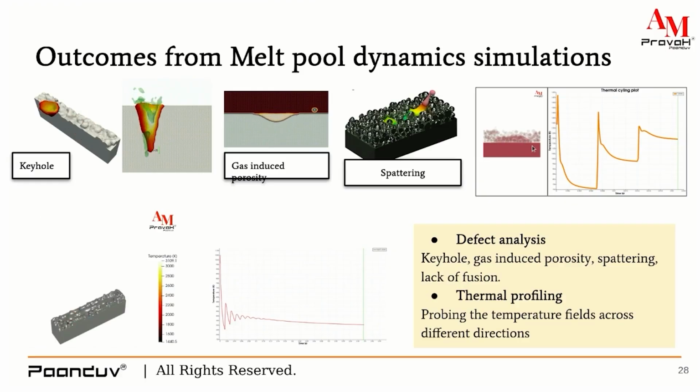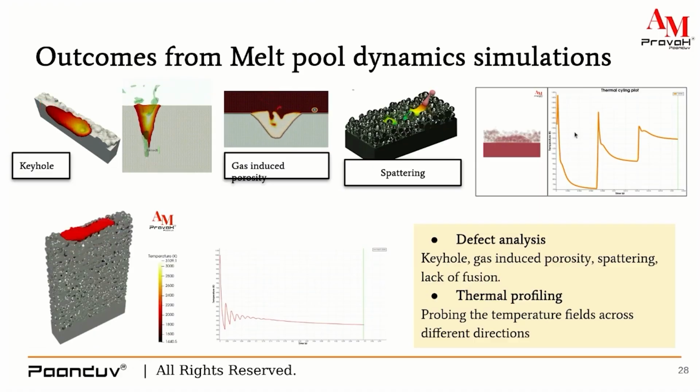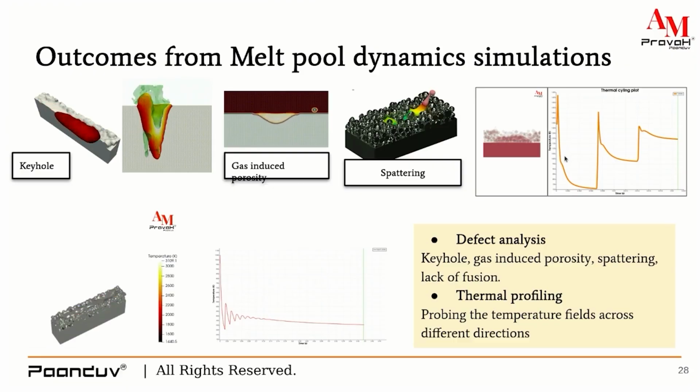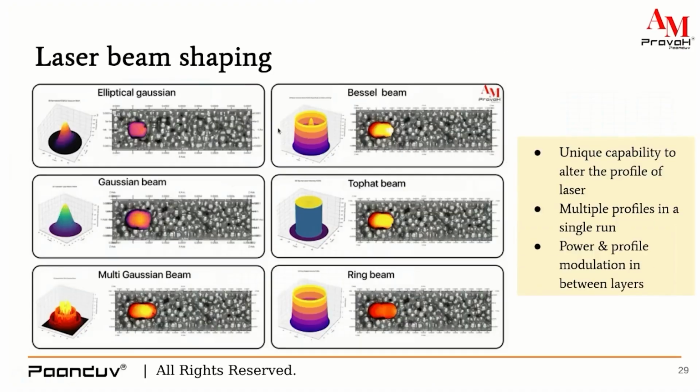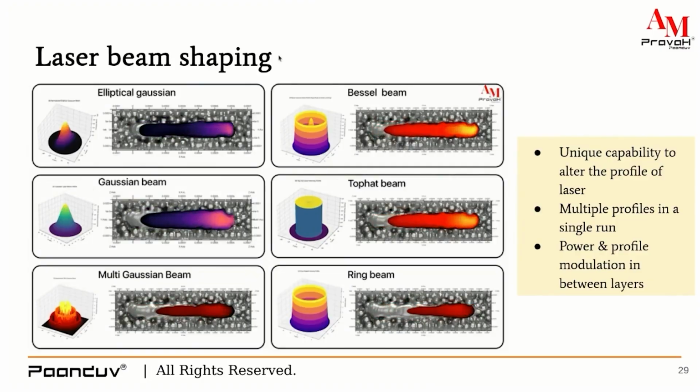Now moving ahead from laser powder bed fusion to wire based laser additive manufacturing systems. Here the feedstock is wire, and wire is interacting with the laser at all times. Wire is at a certain angle. With the scanning speed, with the feed rate of wire and the clearance provided between the substrate and the wire, you create these elongated structures, and these are used for high scale build processes.